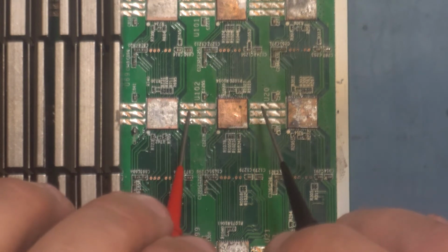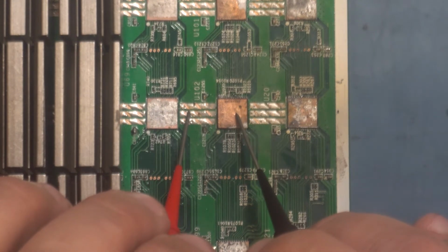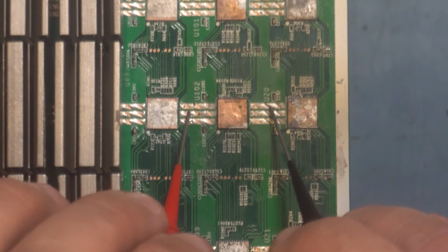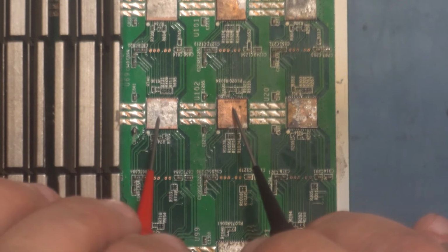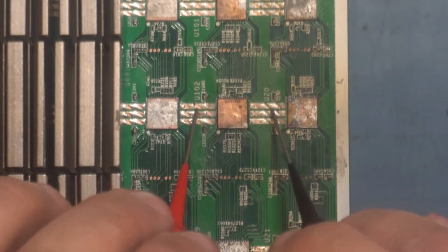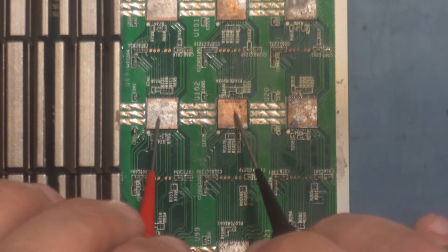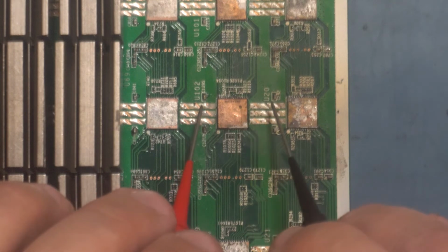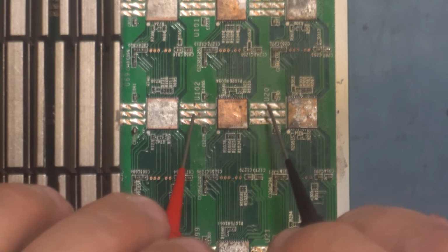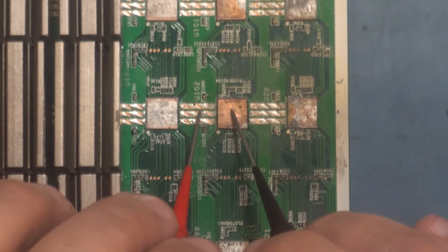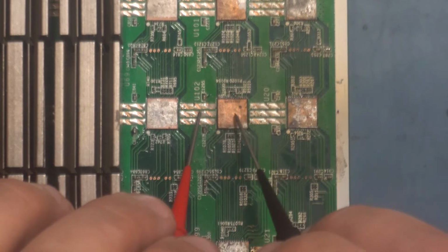This is the ground, and the top of the chip in number 2 domain, the ground of this chip is really this trace right here. So measuring this is really the equivalent of measuring this. And when we measure domain voltage like this, if it's the equivalent of measuring from trace to trace like this, then you're really measuring the voltage difference across this chip or this whole domain, because they're connected in parallel, right?